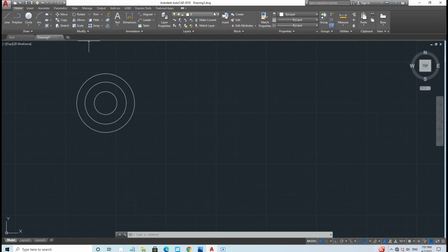Now let us draw a guide. So at the ribbon panel in layers, choose guide or the yellow. Then we're going to create a line from the center downwards. Click ortho mode. The measurement is 1.5. Escape. And then another line from here to the right, measuring 2.62. Escape.